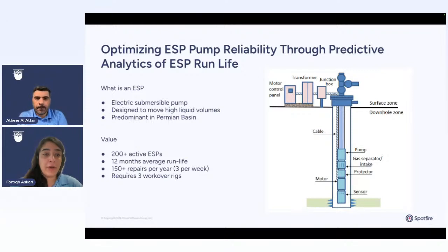Now, why would an electric submersible pump fail? There are many reasons why different kinds of pumps fail, but in this particular case, some of the reasons could be the process conditions themselves, right? Typically we would have gas interference, depending on when we're operating the particular well. You could have sand coming through your pumps, which can potentially cause erosion and different types of failures of your equipment.